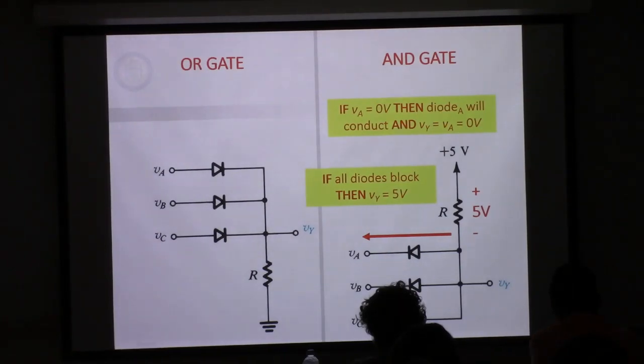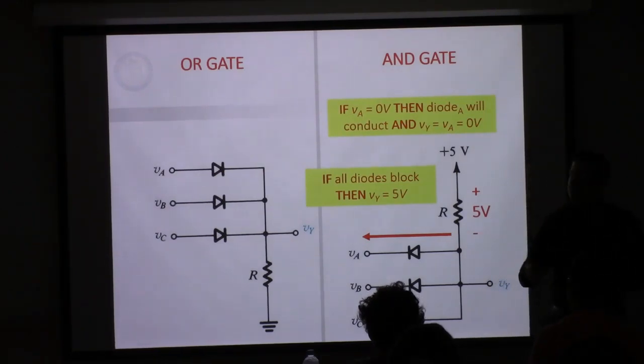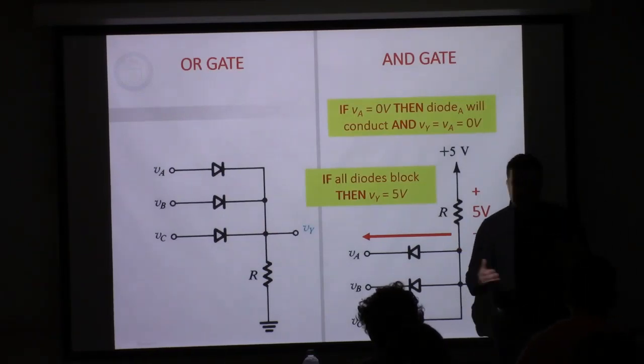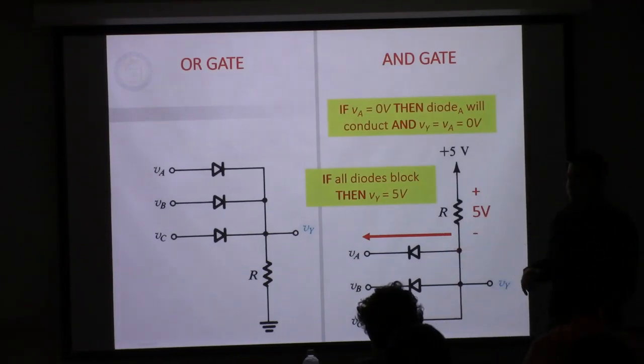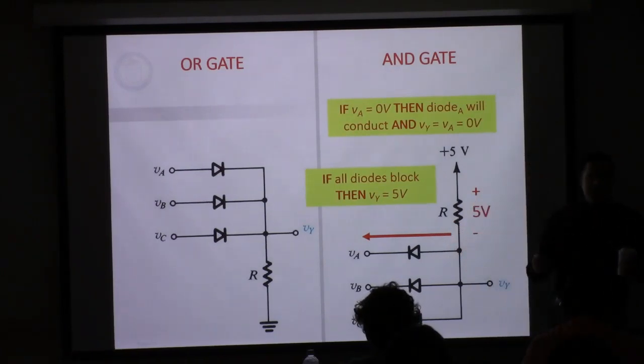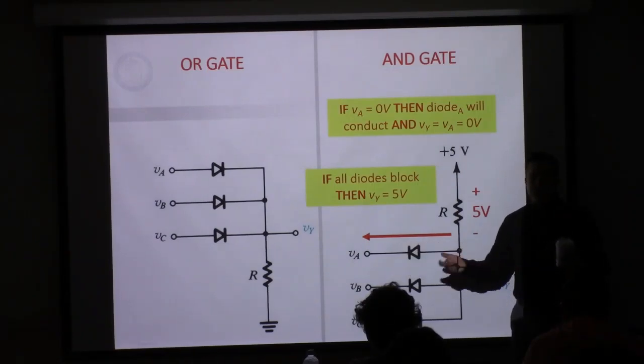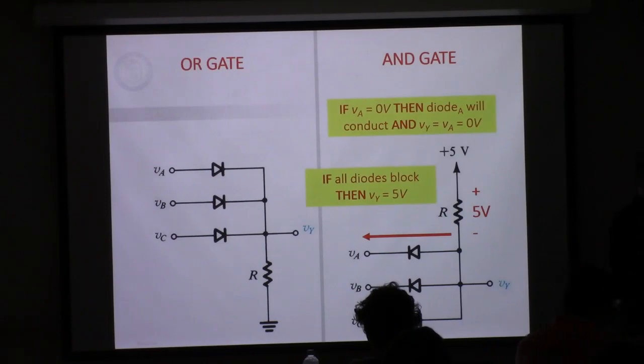So doing these diode problems, especially when we're employing the ideal diode model, it goes back to just regular old circuit analysis. Because the ideal diode is just represented as short circuit, open circuit, short circuit, open circuit. And when you're doing this type of analysis as part of your homework on your own, it may make sense to redraw this circuit for the different cases, putting in short circuits and open circuits. I think that helps. So that's the basics. Another example application is using the diodes to create these logic gates.